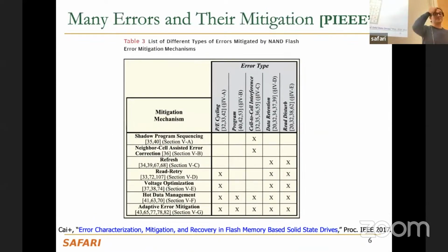So error management is a big task of these controllers, as we have seen in DRAM. In DRAM, we talked about robustness issues, retention issues, etc. Refresh, those are essentially error management issues, right? Refresh is, in my opinion, an error management issue, an integrity management issue, because if you don't do that, you get errors. The reason we're doing refresh today is to prevent errors and data corruption, to maintain data integrity. True for RowHammer as well.